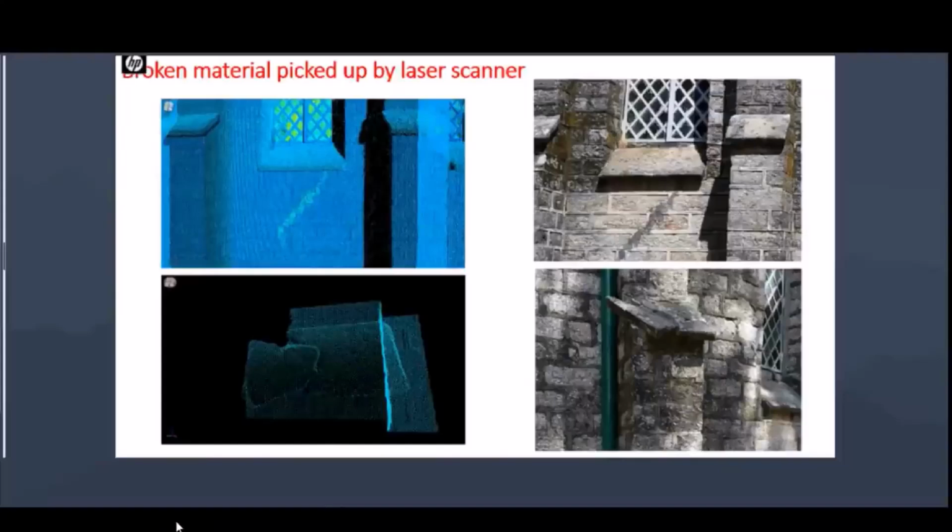Now, to identify the cracks of any dimensions, be it smaller cracks, minor cracks, or major cracks, what we have done is we have tried to use the intensity image as well as the depth and the range data. So RGB image, that is the normal photograph, and the depth data from the terrestrial laser scanning, we were able to generate this depth data.